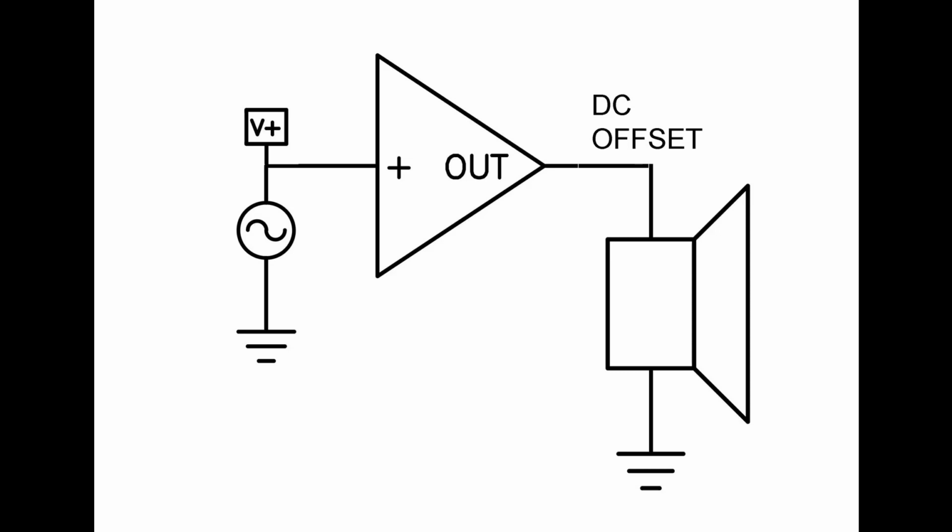Another angle, if you have a power amplifier that is DC coupled at input and output, you can introduce this current by driving the input with a little bit of DC offset, giving a larger DC at the output, as illustrated in this diagram. 1 volt DC from an amp's output into 5 ohms will give you about 200 milliamps and will also bias the output stage of the amplifier, possibly killing 2 birds with 1 stone.